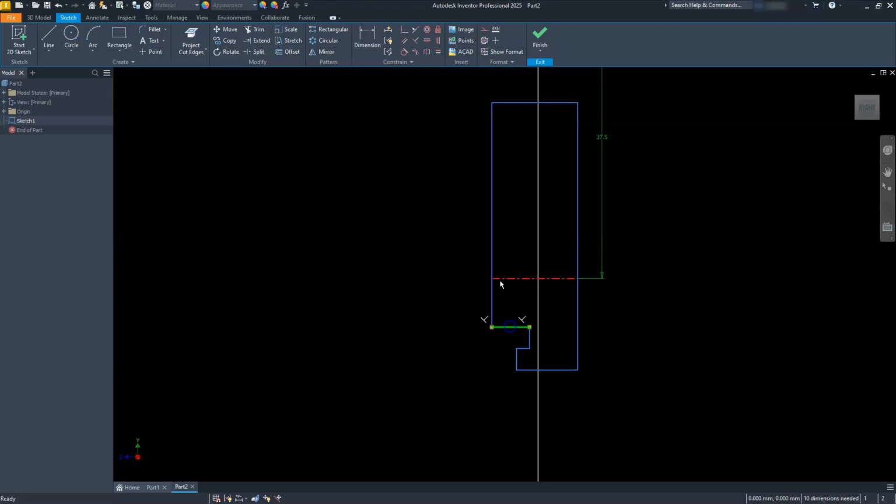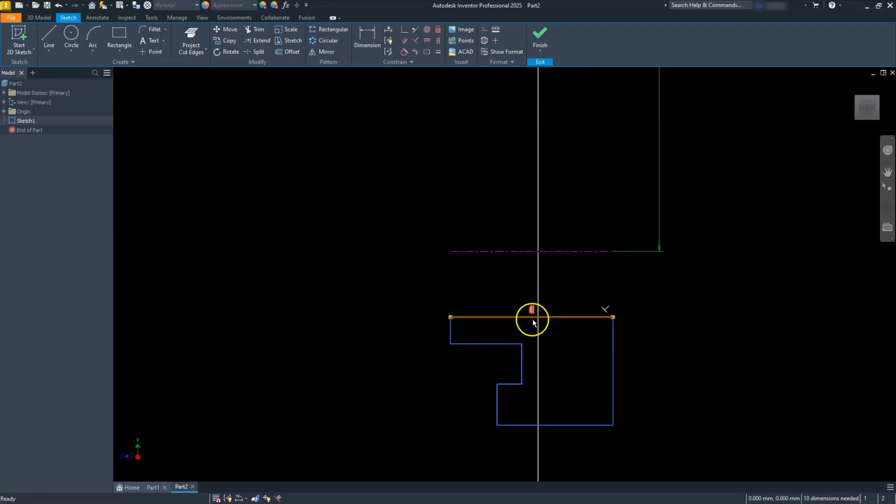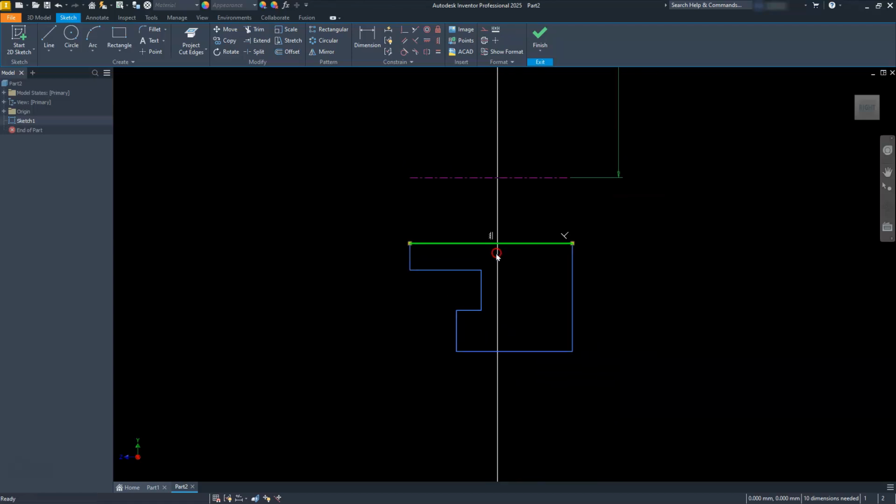And then here. And then finally this one. Okay, so I know it looks a little weird here at the bottom, but everything will work itself out. Next, I need to go ahead and put its diameters on here. So I'll use the distance command, and I can select this center line here. Then select that line there, and it's asking me what is the diameter of that. And remember, this is our big one, so that's going to be 64.